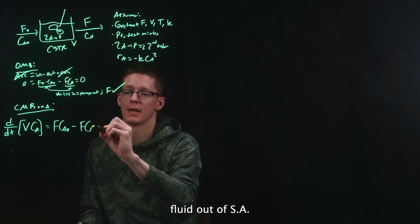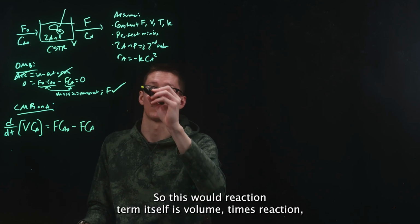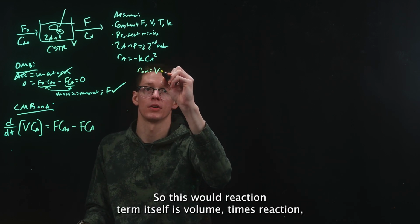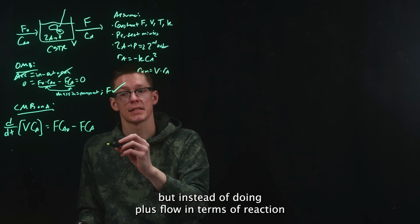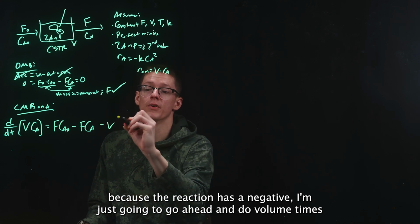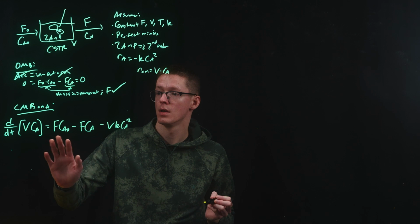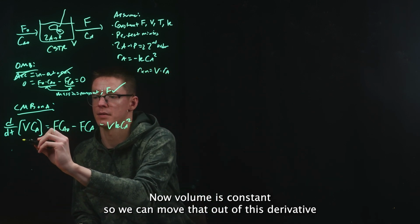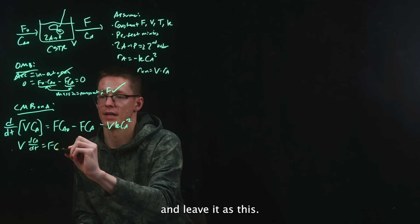Fluid out, F Ca, and we have a reaction term. So this reaction term itself is volume times reaction, but instead of doing plus volume times reaction, because the reaction has a negative, I'm just going to go ahead and do volume times the reaction already plugged into the expression. Now, volume is constant, so we can move that out of this derivative and leave it as this.